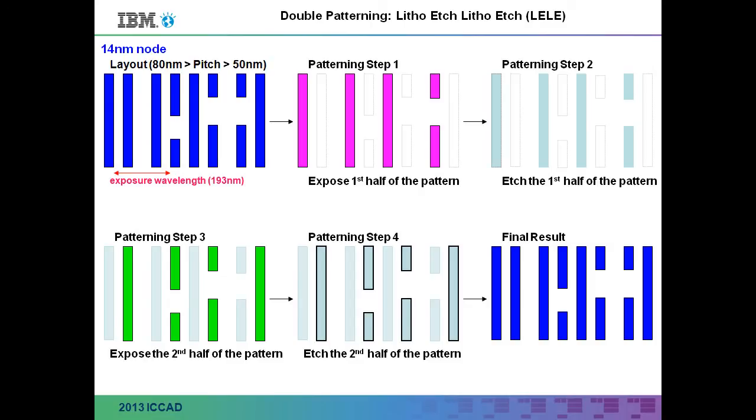You could think of it as we can afford to donate about 20% of our critical feature size to overlay. Achieving 5 nanometer alignment accuracy is extremely difficult. So that all adds up to roughly 50 nanometer minimum pitch based on the overlay capabilities of known tools. There are people that do much more sophisticated calculations, and they also come up with 50 nanometers. Plus or minus a couple of nanometers is a fairly well accepted cutoff in the industry as to the limit of this kind of double patterning technique.